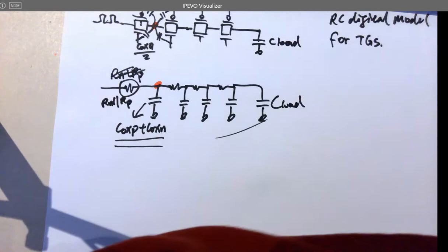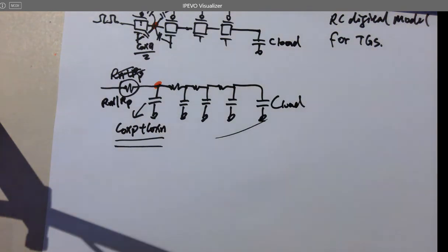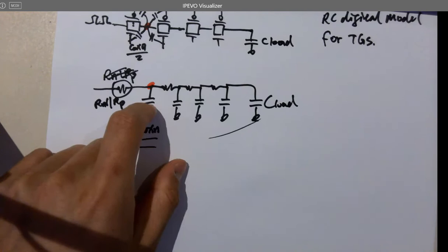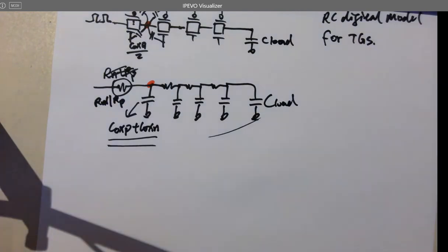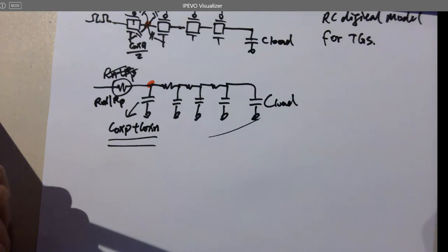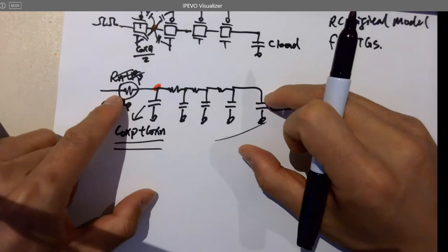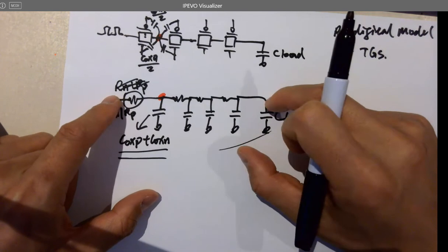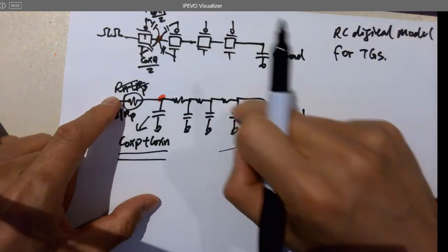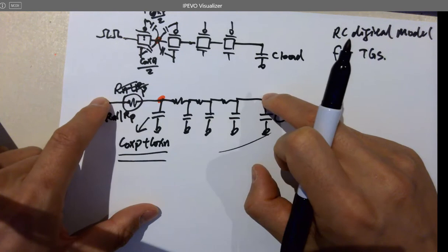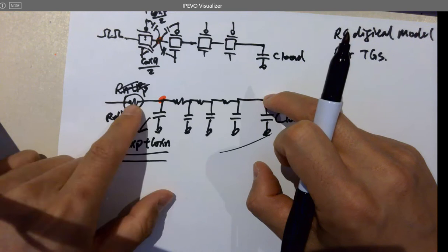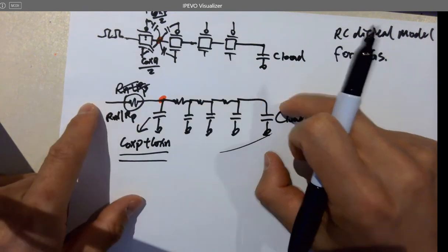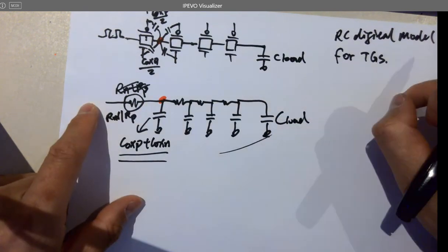Remember how we calculated the time delay in a circuit like that? We did it for the RC model. And remember that was like 3.4 RC for the total time delay. But just look at your notes. Go back to that lecture. Okay, we did it in the past. If you can model everything like that, the time delay from here to here will be 3.4 N, where N is how many stages you have. So 3.4 times N times RC. Okay.